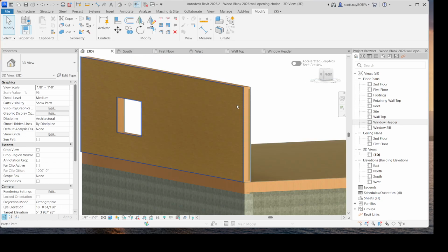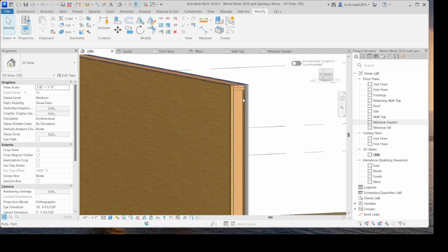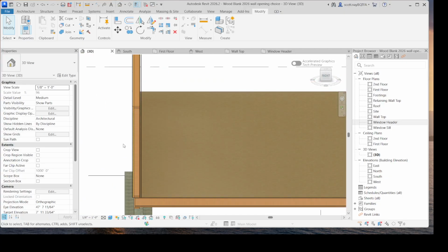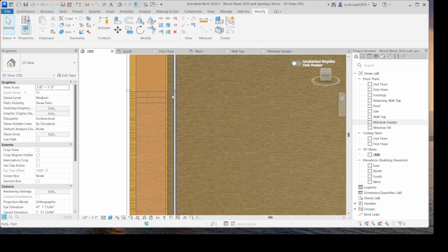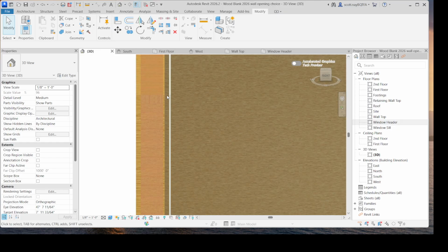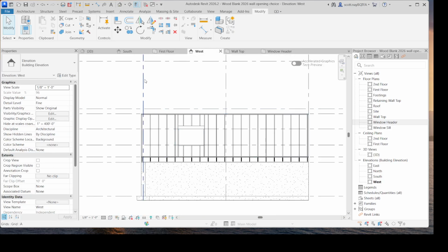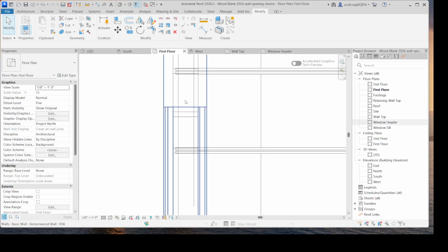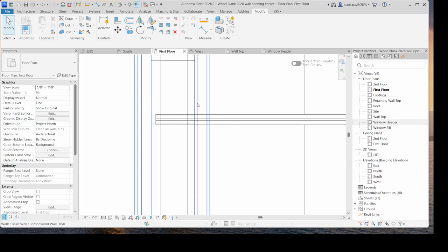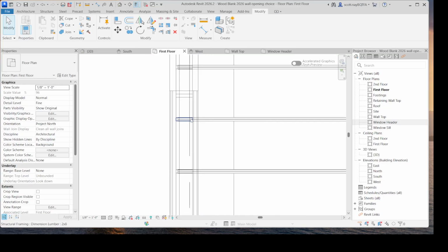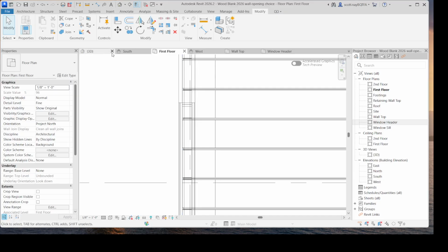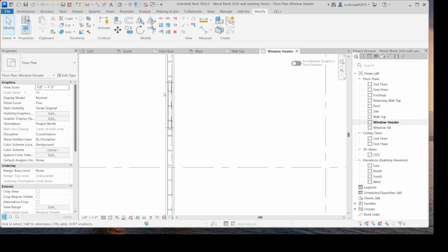All right, let's start with the interior wall here. We've got this gap for some framing. It's going to be 2x4s, and they're going to go the opposite direction. So, wrong one. Instead of going this way, they're going to come across this way, and then in between we will do insulation. I'm not even going to bother with beam systems on this one for a couple reasons. Most importantly, it will just glitch on me.